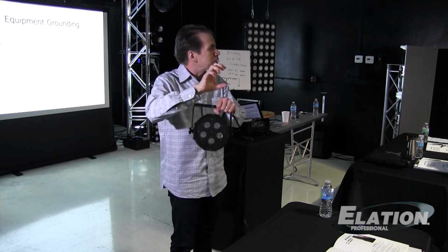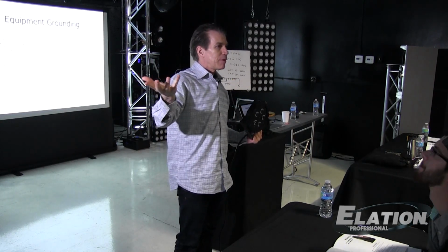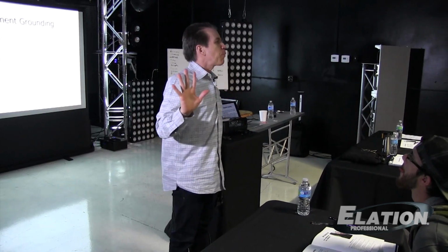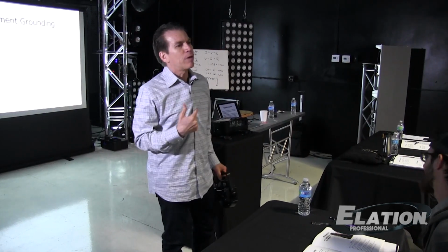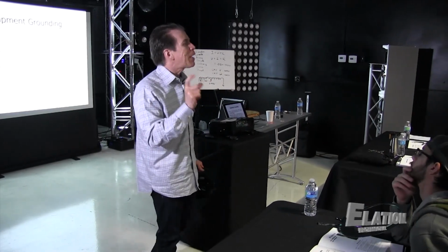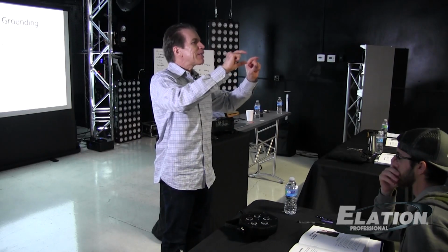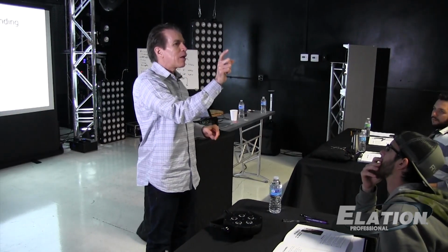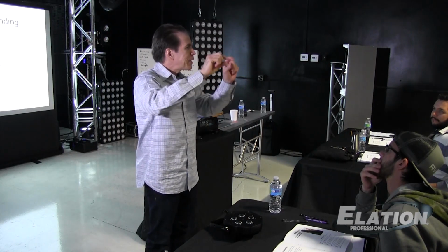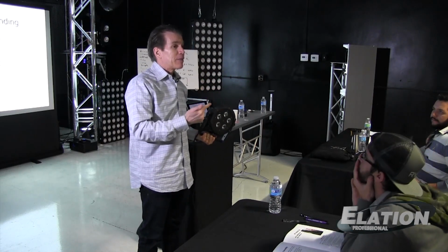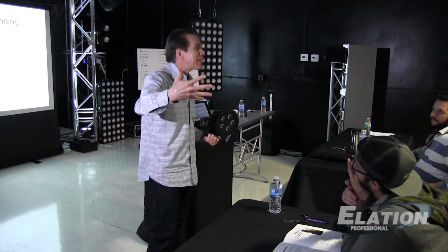But if I use a truss protector, it's not. So if you're going to use truss protectors, just make sure the truss is bonded at some point. But a better thing to do is, they do make truss protectors that are little, made of stainless steel. They're about that long, little rectangular pieces of steel that fit between the truss and the clamp and protect it. And because they're metal, they bond it. So now you're protecting the truss and you're bonding it at the same time.